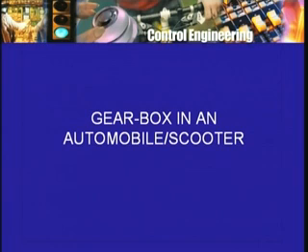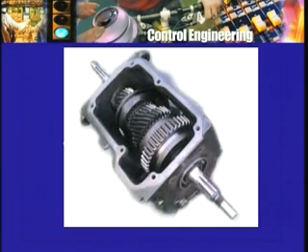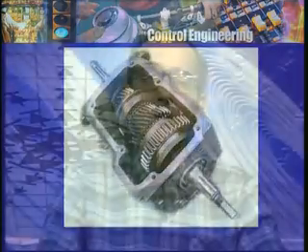In fact, something like this happens in an automobile. As you know, in an automobile and even in a scooter, one uses the gear mechanism and one shifts or changes the gear. So what's happening there? You have one shaft and you have another shaft. They don't run at the same speed and they don't transmit the same amount of torque. You have gear wheels on the two shafts, and depending on the ratio of the teeth on the gear wheels, the speeds and the torques have a certain ratio, and by changing these gear wheels you can change the torque ratio and the speed ratio.